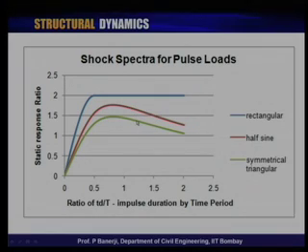If I get the triangle to go really, really slowly, see, it goes to 1. So, in other words, if Td by t is large, the triangle really goes up slowly, it tends to 1. So, all of these points that I have made come out directly from this shock spectrum. And that is the reason why I showed the specific problem that I looked at, the rise time. So, that is a very interesting point of the pulse characteristics.